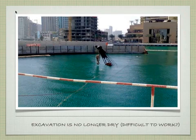Do you have a question? You never mentioned where, when they hit the water, what do they do with the water? They have to find a way to dispose of it. And that's dependent on the site. So sometimes it goes into trucks and they truck it away to somewhere where they can dump it. Sometimes they can dump it into the groundwater system. Sometimes they can take the water that's pumped here and pump it out into another body of water. It depends on how toxic that water is as to what they're going to have to do with it. Certainly if it's really toxic, they're going to have to figure out a way to filter it or dispose of it in a good, clean manner. Recognize that this water often can be muddy and icky, and that's a problem too.